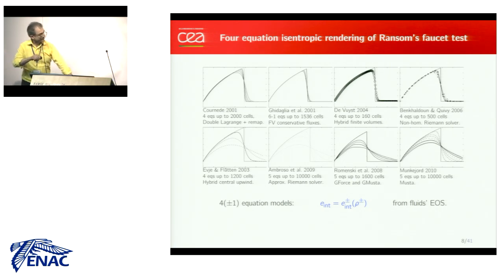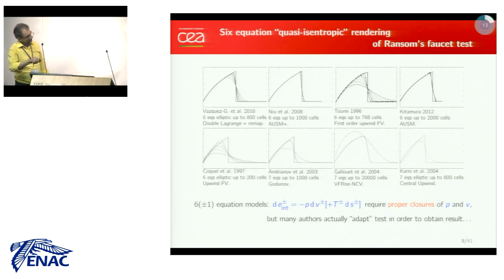Now, if you carry out this simulation with a more extended model, with the 6-equation model, where you add this time evolution equations for the internal energy, so you integrate basically de equals minus p dV plus T dS, that should be 0, but happens to be not exactly 0 because you're doing numerics. Well, some people manage to do well. Some others here start producing some really strange artifacts, or ask for an enormous number of cells in the calculations in order to recover something sensible, of course.